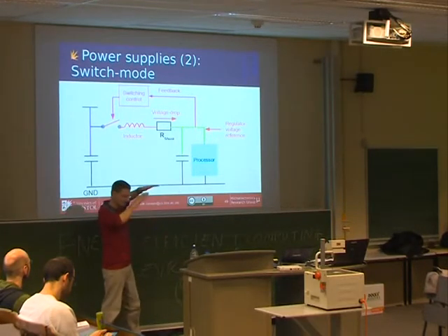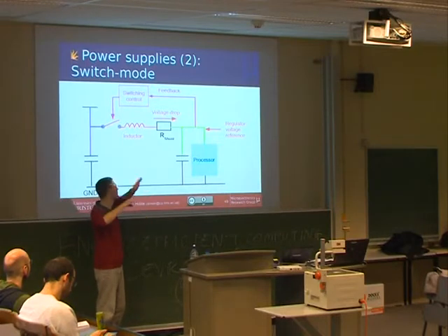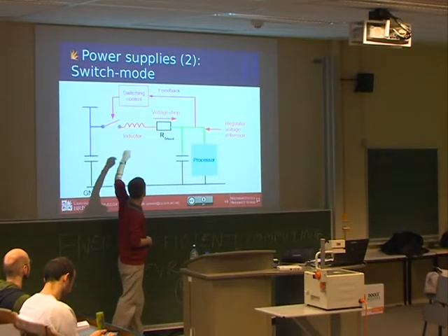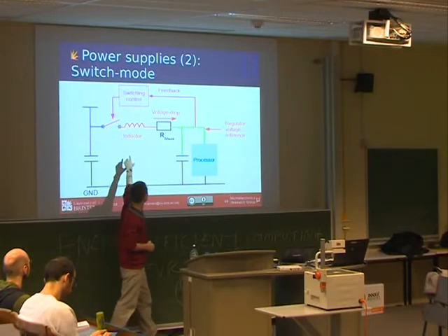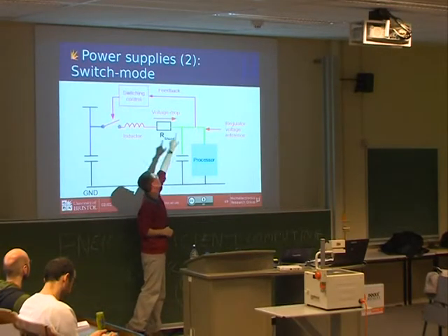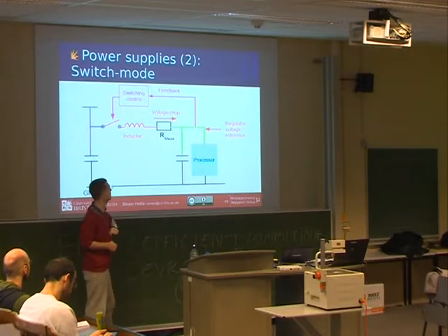Do I need to connect it? And if the voltage is too low, it connects the power supply, if the voltage is too high, it stops. And so this thing goes up and down, 100,000 times a second, and there's a measurement point where feedback comes in to decide whether to close the switch.